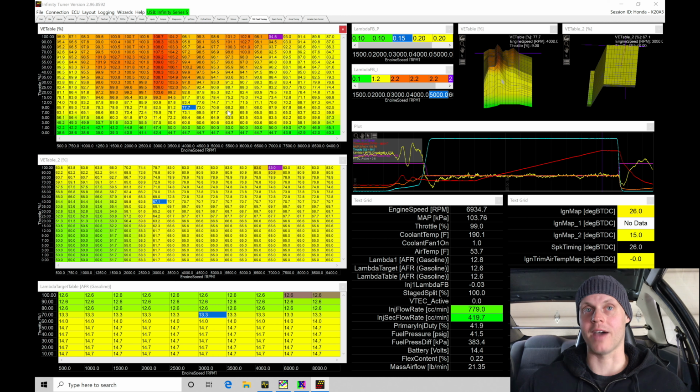Now, we did do a MAF-specific AEM Infinity live training video that's in the Porsche Cayman in our course library. In that video, I was referencing what the mass airflow sensor was flowing in units of pounds per minute. And if we know what the pounds per minute range is, and if it's accurate, we're going to find if we multiply this value by approximately 10, we can translate that into the horsepower the engine is making.